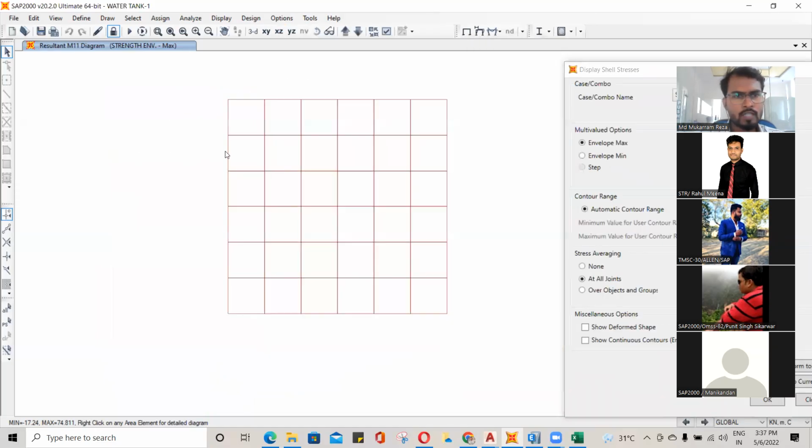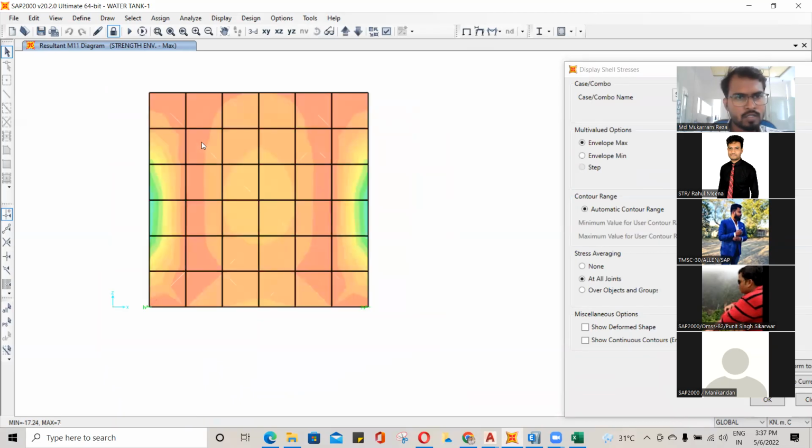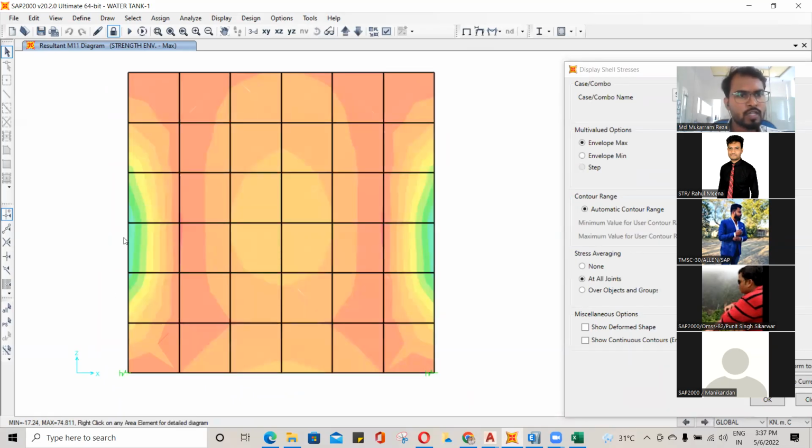See, it's actually the working stress method. Generally we use the working stress method to design the water tank. Sir, here the load combination is like 1.5. It is limit state. If you check the crack width and it passes, it is fine, I think. For checking the settlement, it is only the service. For designing, it is LSM, limit state.